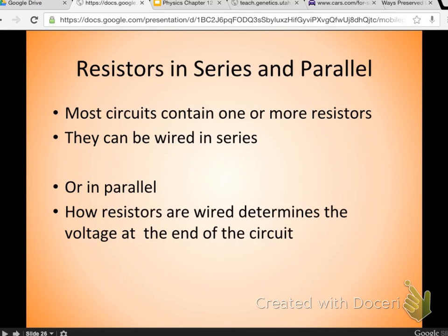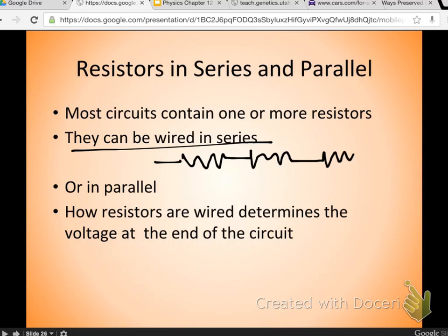Okay, so this is very much what your tutorials were about, and this is what we're going to start with. Wiring resistors in series and parallel. And you had your challenge problem, obviously. So if you wire them in series, the current has no choice but to flow through one before it flows through the other. If you wire them in parallel, the current has multiple paths. And anytime current has multiple paths, it will take them both. So even, this is one that confuses people.